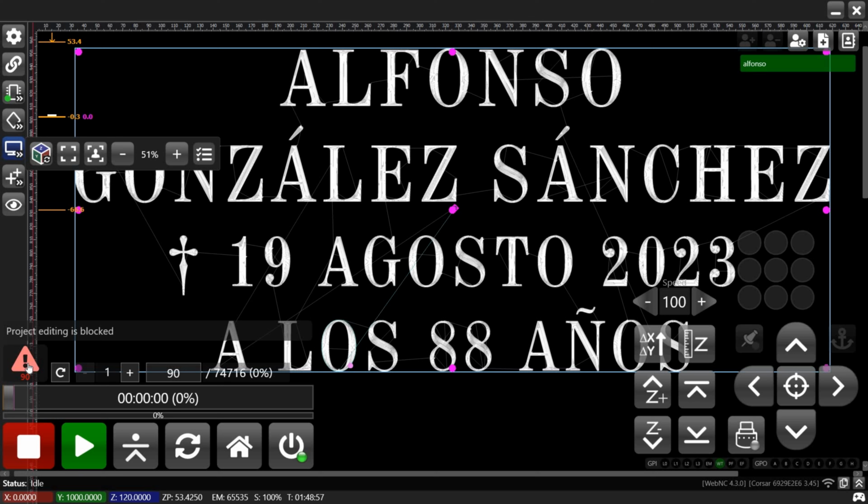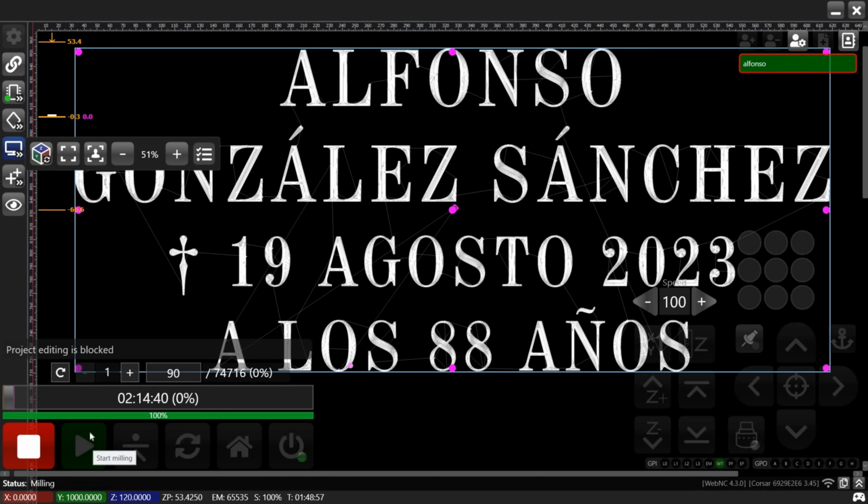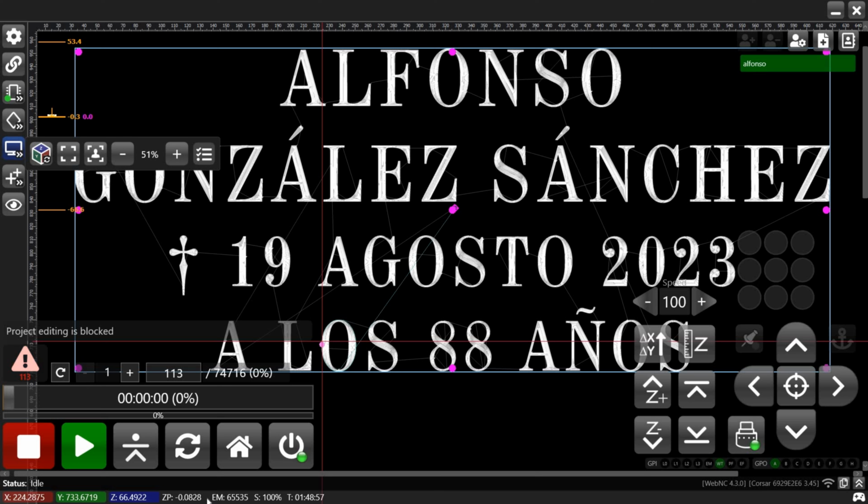Here we see a warning triangle. It shows the position where the work was abrupted. The machine retains the coordinates, so after the restart, it will go exactly to the point where it left off. The machine detects possible failures of the frequency controllers, so in case of failure of an external device, the machine will stop.